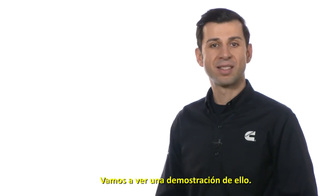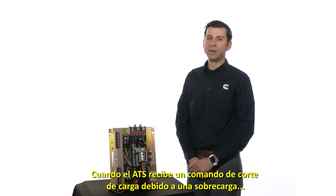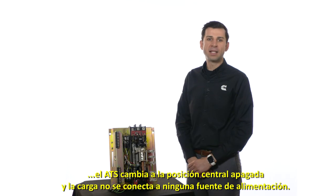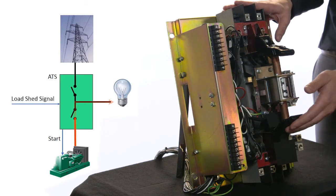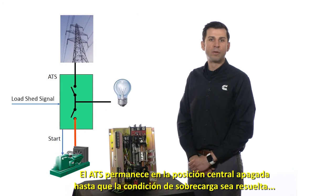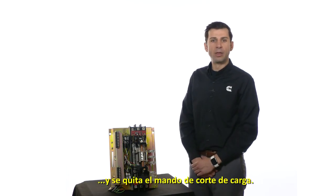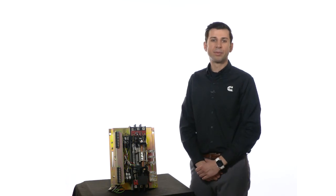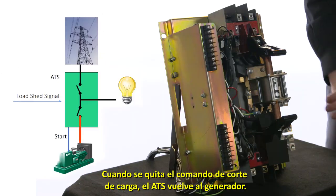Let us demonstrate this. In this position, the loads are powered by the generator. When the ATS receives a load shed command due to an overload, the ATS moves to the center off position and the load is not connected to any power source. The ATS remains in the center off position until the overload condition is resolved, by an operator for example, and the load shed command is removed. When the load shed command is removed, the ATS moves back to the generator.